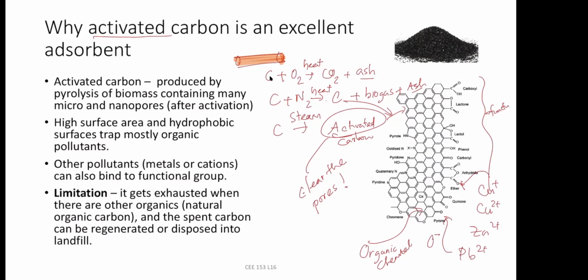The only limitation is that, like any adsorption technique, it depends on the surface properties. So once those surfaces are gone, you cannot continue to adsorb more pollutants. So that's why this activated carbon will be exhausted at some point. You've got to regenerate it by heating it up again, the same way you do pyrolysis, so that you can burn all the surface chemicals, and then you can reuse it again. And every time you regenerate that activated carbon, some adsorption capacity will be lost forever. After a point, it's not economical. You have to dump it.